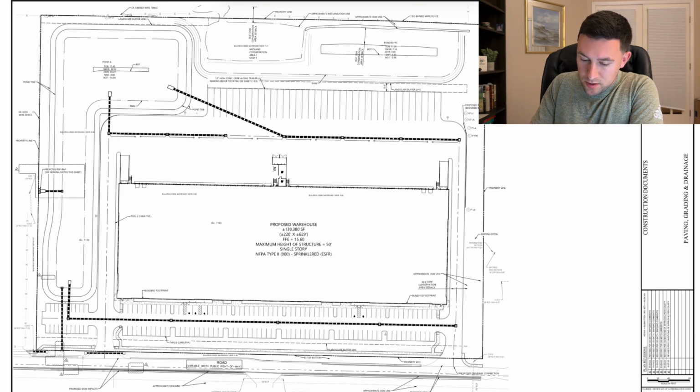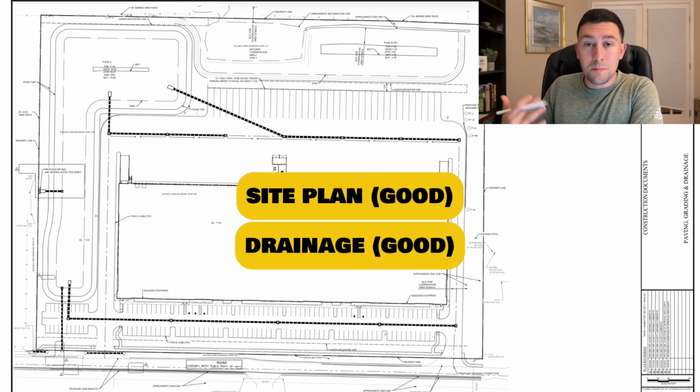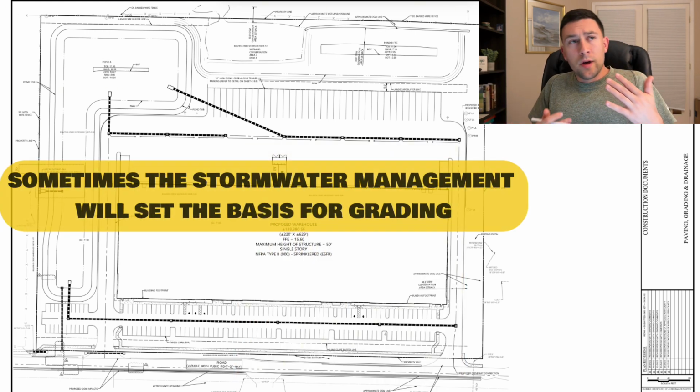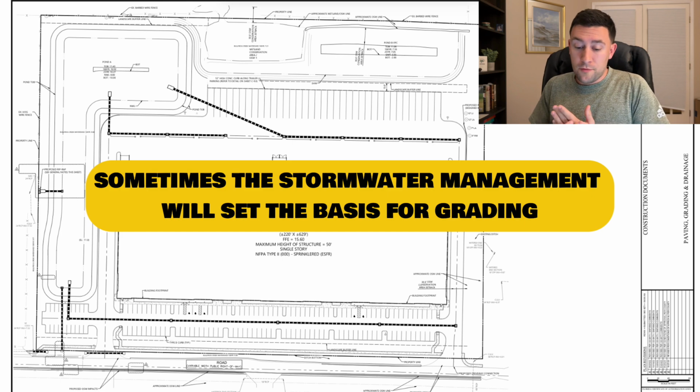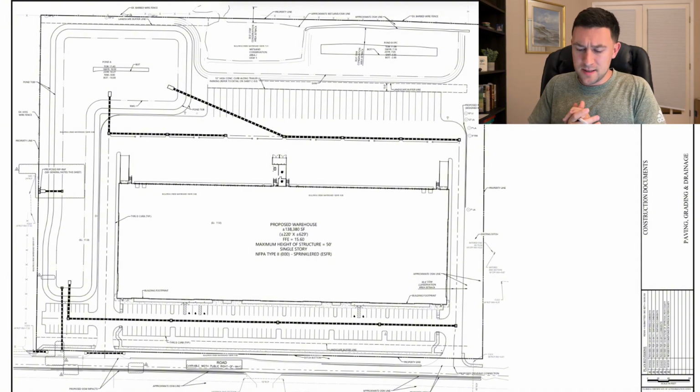So just to kind of put into perspective of where we're at, we've nailed down a site plan and we've nailed down the stormwater management of this property. The stormwater management is important because typically with at least Florida and where I'm from, a lot of these design levels, these design high waters of the pond will actually set some of the grades and the low points, but we'll kind of get to that later.